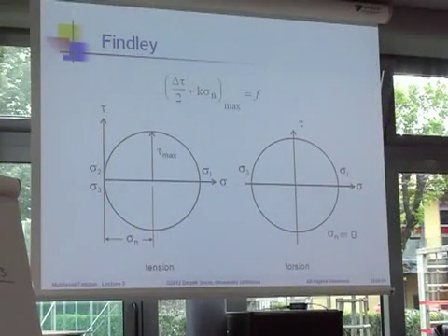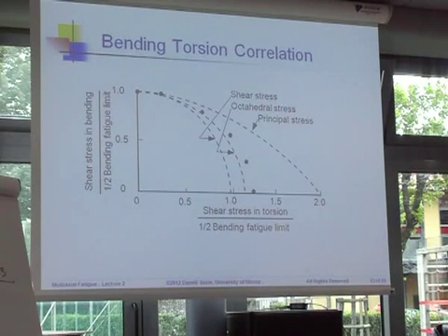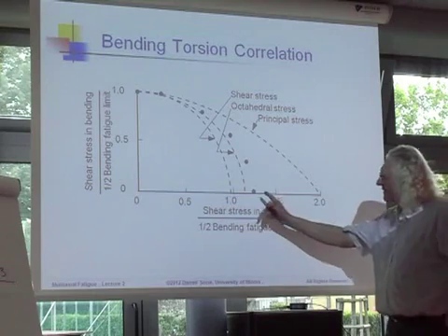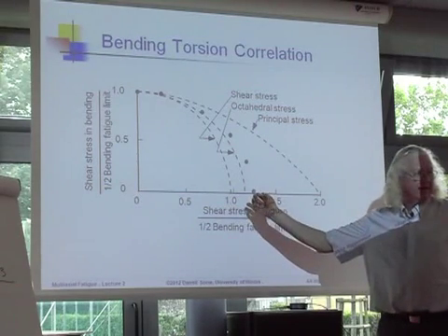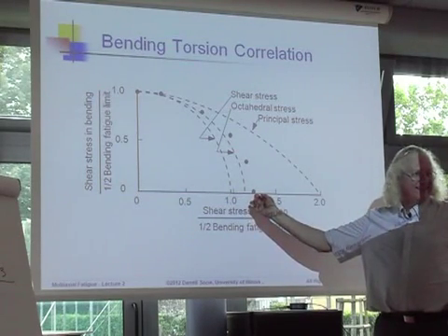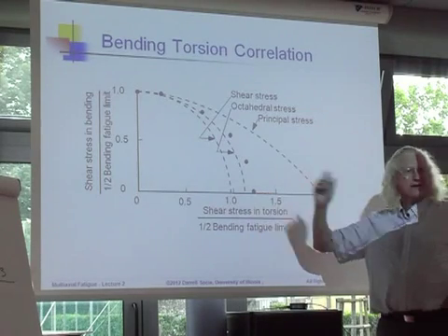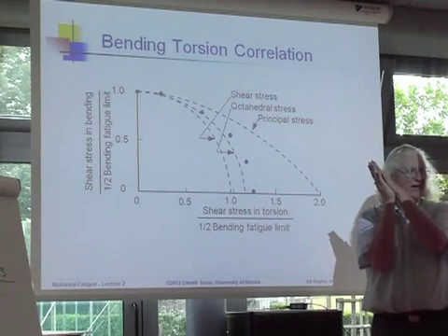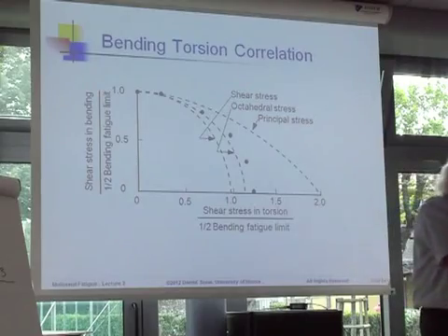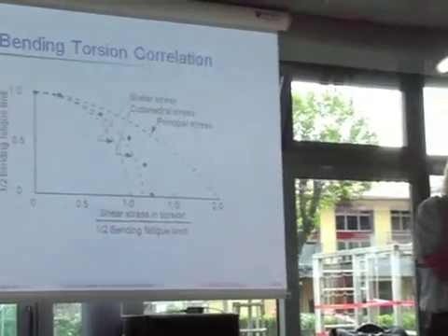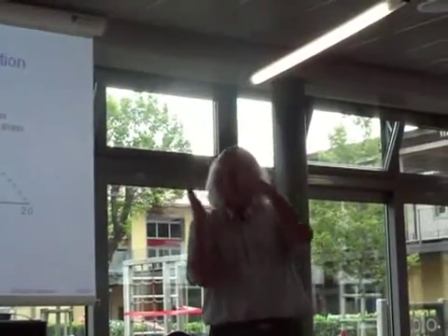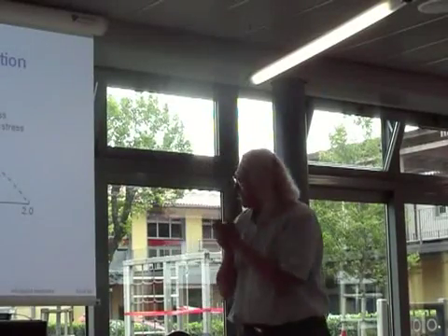Many of them. You need many, many of them. And that's why when I started this, I told you this correlation was a mistake. Finley has the correct physics. There is a difference between tension and torsion loading, and this difference is the normal stresses that act on cracks.